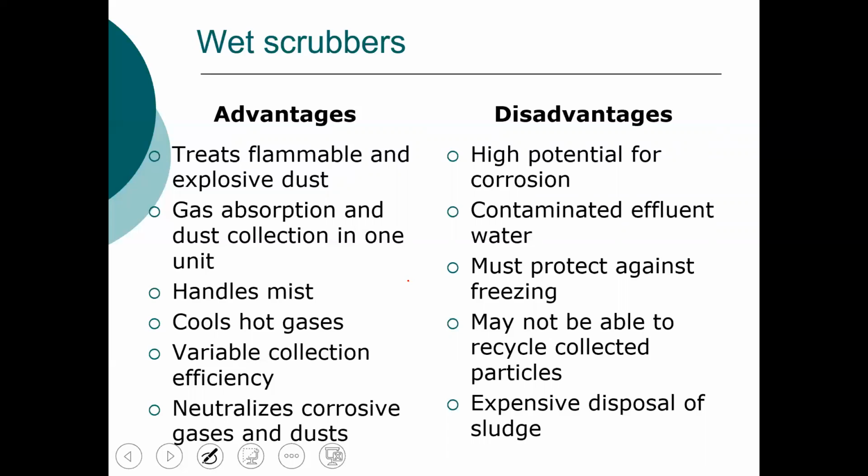So depending on whether you want to recycle a material, wet scrubbers may or may not be the optimal process. And then lastly, since your contaminants end up in water, you end up with an aqueous waste or sludge that will typically have a high moisture content. Therefore, you've got a high volume, and either treatment or treatment and disposal can be expensive because of that.